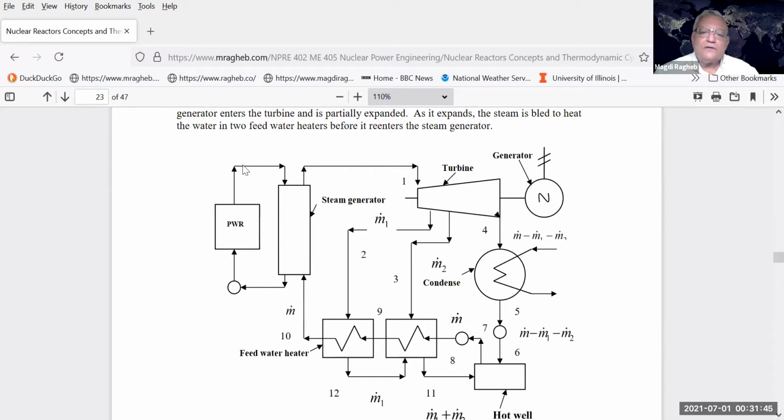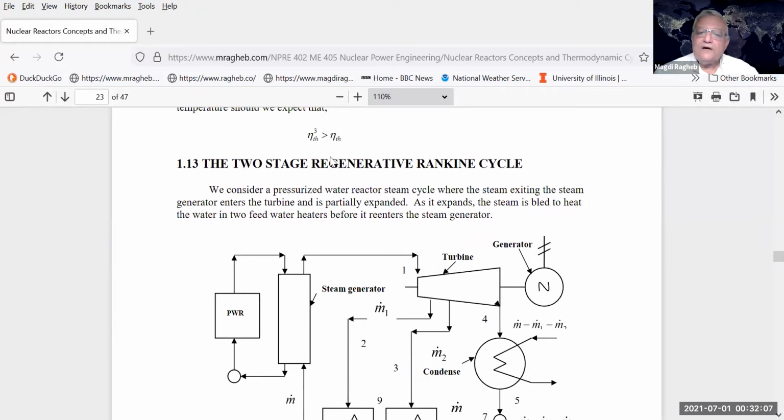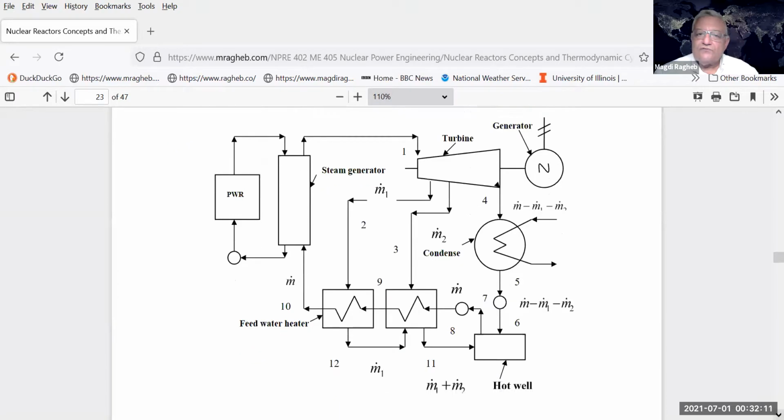We generate the steam. We heat the liquid after pumping it into the core. The liquid goes into a steam generator where water comes in from feed water heaters, turned into steam and goes to a turbine to the electrical generator. The regenerative process tries to enhance the efficiency or decrease the amount that we have to devote to the flow system by bleeding steam as it expands through the